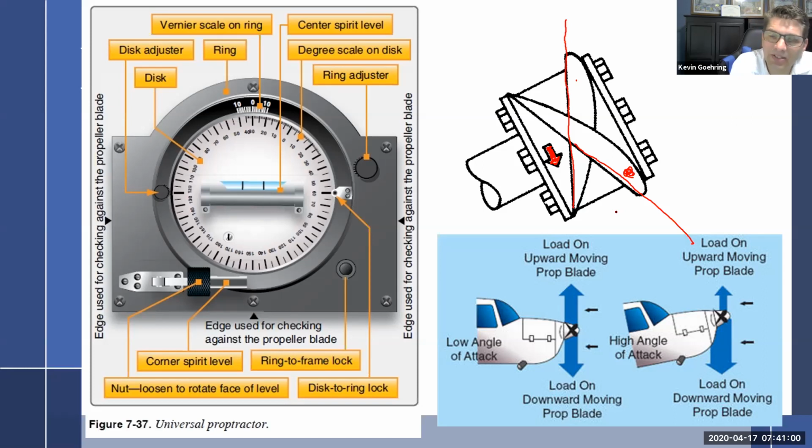And that means the right side of the propeller has more of a grab to it than the left, which means you're actually going to start pulling the right side of the aircraft over towards the left, and you will make a left-hand turn because the right side is taking more of a bite. So that is called P factor, and that makes the airplane go to the left.